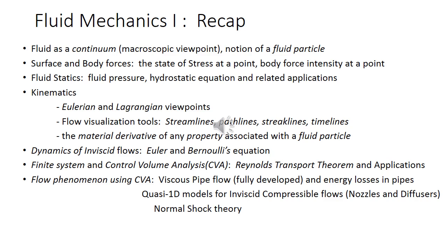So the ions can experience electric and magnetic fields also as a body force. So body force, remember, is caused by external force fields. They are imposed on the fluid. They may get influenced by fluid motion, but their origin is not related to the fluid motion. They are because of external force fields which are present, like gravity and even electric and magnetic fields for suitably charged or ionized fluids. So this is the concept of surface and body forces.